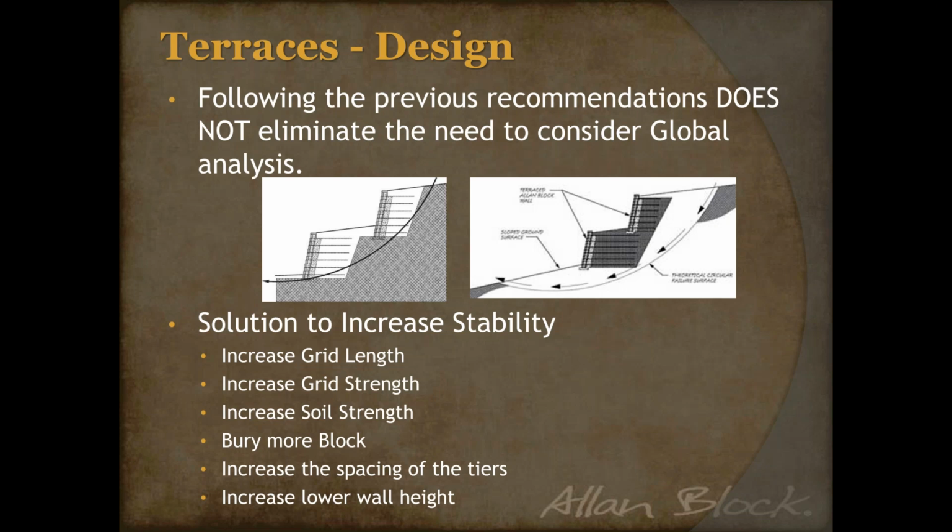You could increase the spacing of the tiers. I can't guarantee this will always solve the issue, but it could help because by spacing these out, you have essentially changed the overall, or the effective, slope of this site, making it softer and allowing for larger safety factors on that slip arc. That's a potential. Doesn't always work, and maybe you don't have the room on your site to accomplish that. Those are all things you've got to think about.